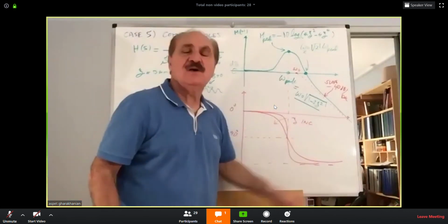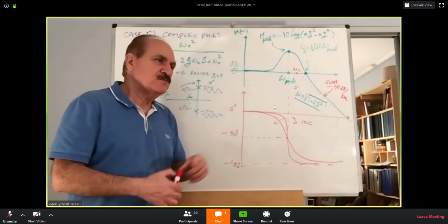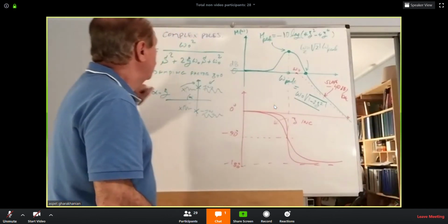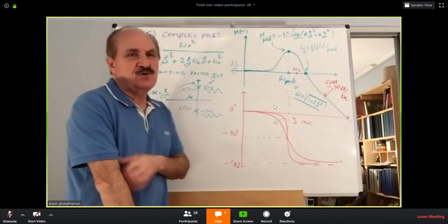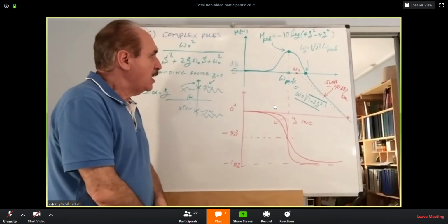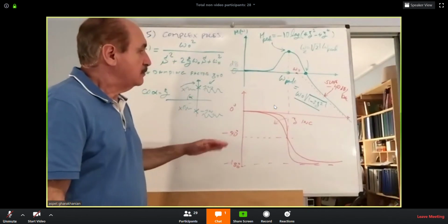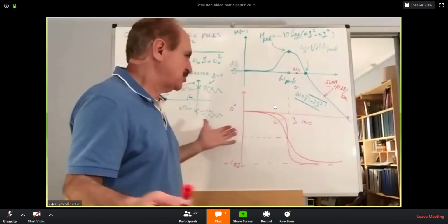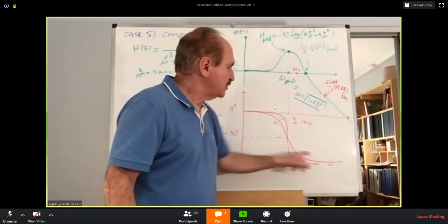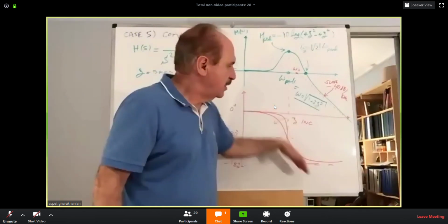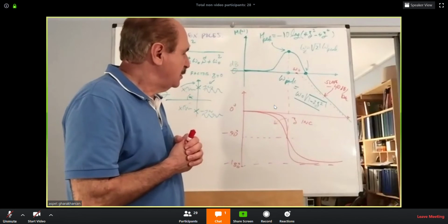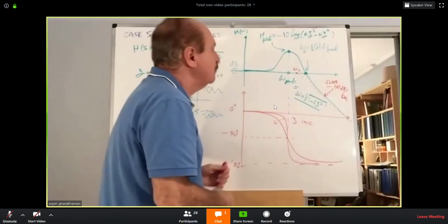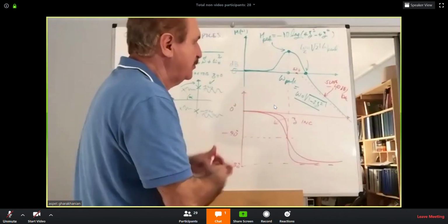So this is the general phase behavior, which is, I know, a little bit more complex, but that is how a complex pole is going to behave. Again, it is difficult to come up with a linear approximation to that, but it's always possible. You have to see what the curve is, create some kind of straight line approximation, and incorporate that with the other poles and zeros. I admit it is a much harder exercise.